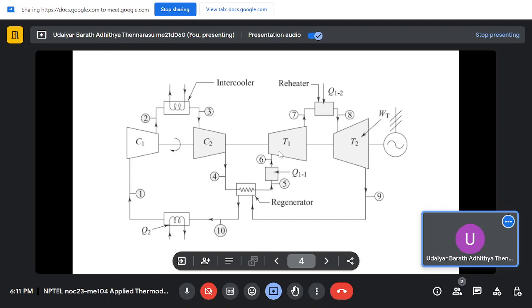So the fluid runs through turbine 1 to state T7. Then you reheat it, ideally to temperature T6, so you are again raising the energy of the fluid. Now when you run through a turbine for that pressure ratio, your work output will be larger compared to what it would be without reheating. If you assume two turbines without reheating, the enthalpy at 7 will be H7, so H7 minus H9 would be your work output in the second turbine.